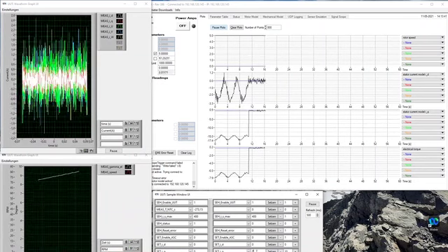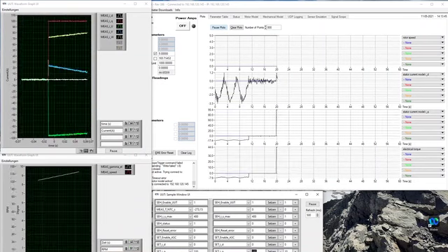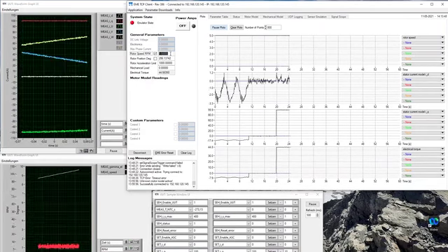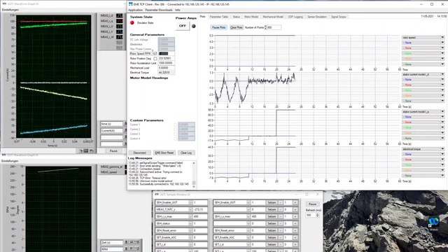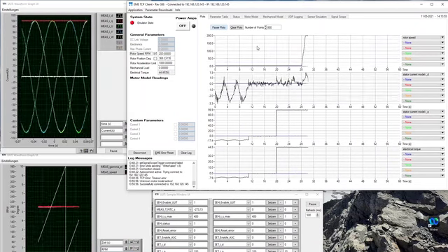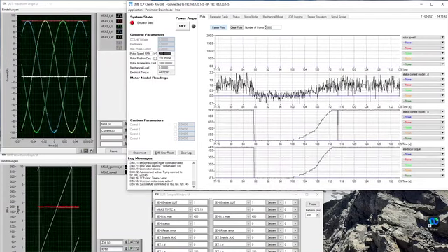Then the set point of the Q current is set to 100 ampere. It can be seen that the actual Q current goes to 100 ampere while the D current remains 0. Now, the rotor speed is ramped up to 200 RPM. Then it is increased up to 1000 RPM.